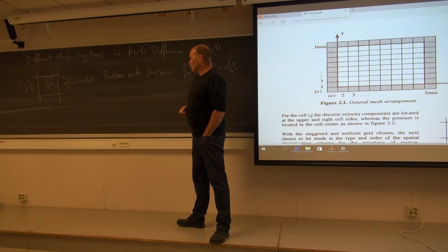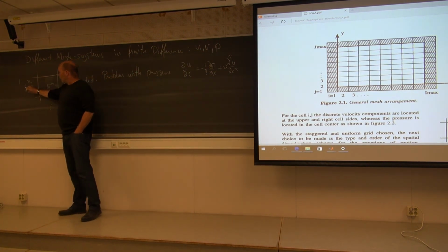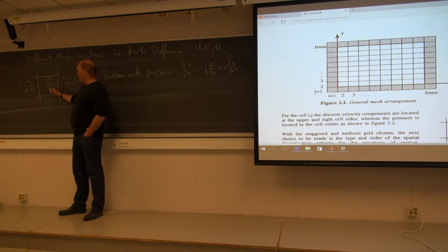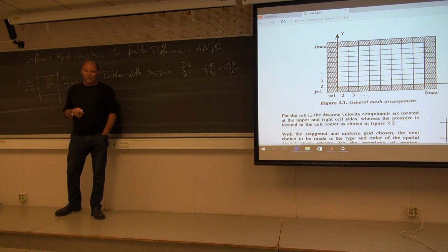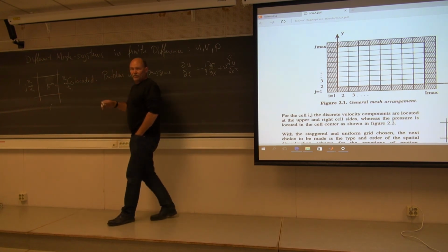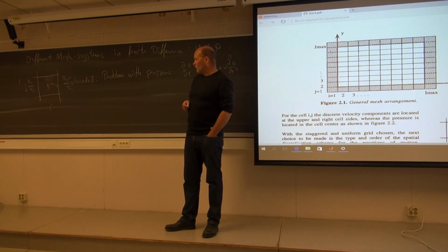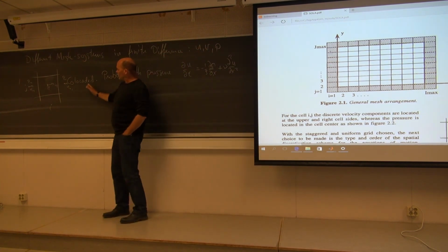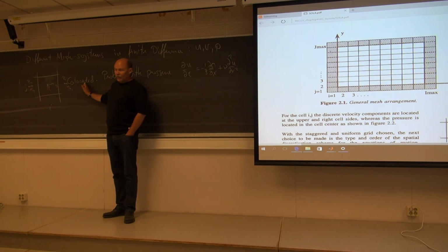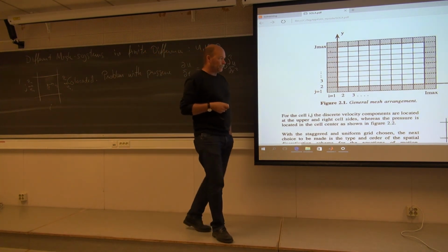You could, of course, cheat. You don't have to use a second order accurate derivative. You could have used a forward derivative or a backward derivative or something like that, just to include the center point with the pressure into your scheme. Nowadays you have ways to include it, so co-located meshes are becoming more and more popular again. But in the early days it was discarded. They didn't use it due to this pressure problem.